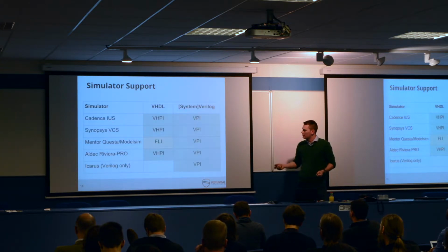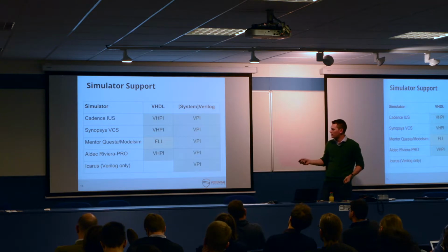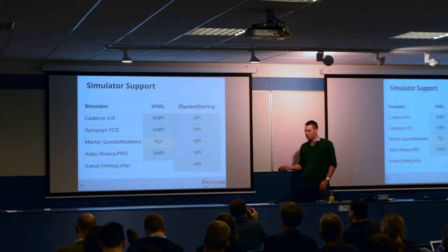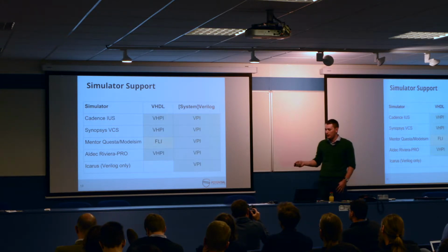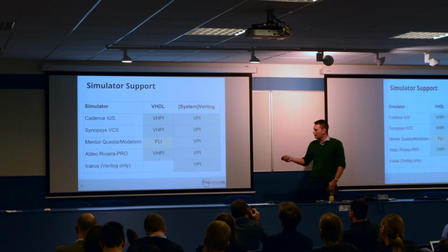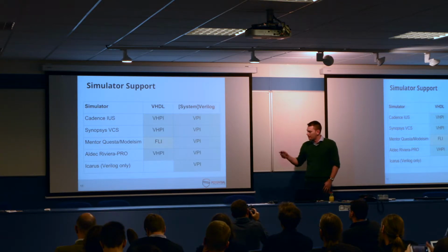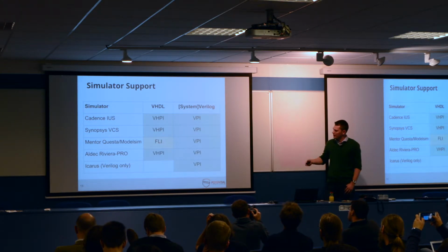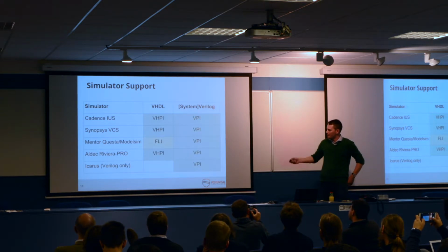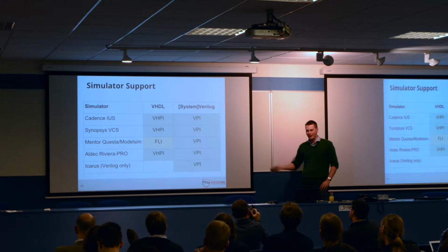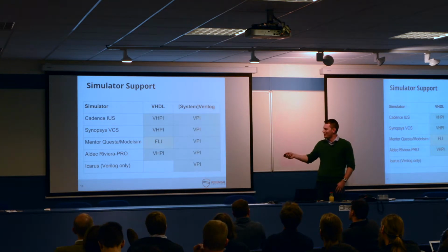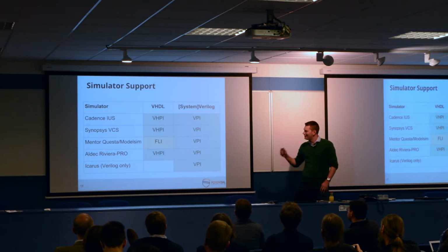Okay, simulator support. So we support all the major commercial simulators and some of the open source ones. Anything that's in theory compliant with VPI or VHPI should work with Cocotb. FLI, Mentor don't like us for some reason, so we've struggled to get a license to develop FLI. It did work at one point, but it's a bit rotted, I'm afraid. So if anyone wants to donate us a Mentor license, or they're using FLI, then get in touch.